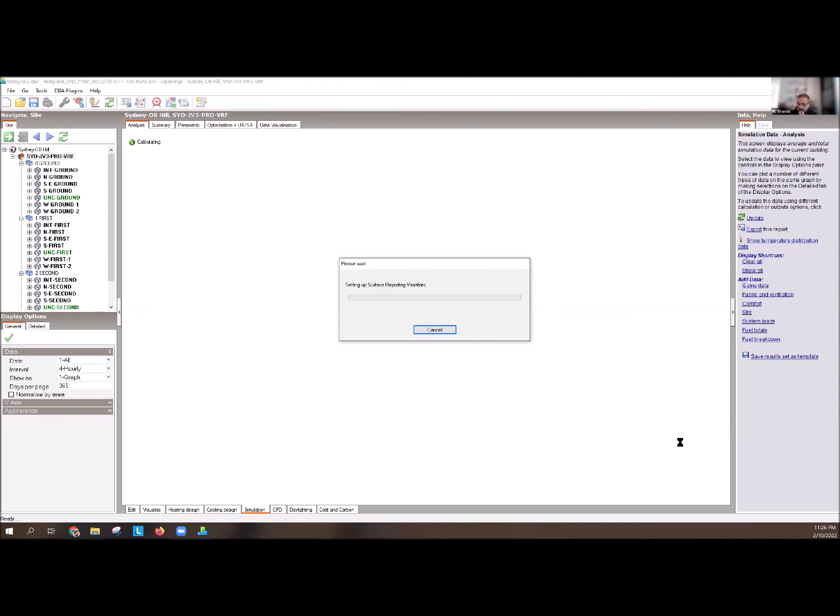Okay, so for looking at how the window performance can be altered, you can use this method. So you may want to go and talk to some glazing suppliers and find out what kind of performance numbers you can get. And by the way, when you use the simple window configuration, you can include the performance of the frame in there as well. So when you give the U value, I've given it 5.6, that can include the performance of the frame.